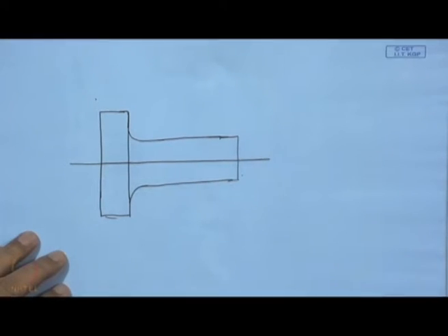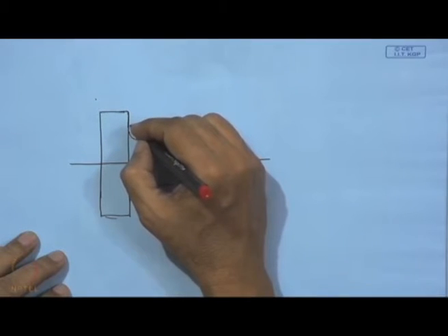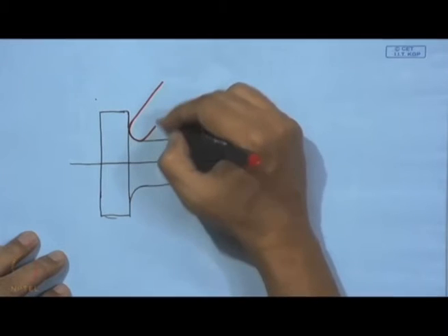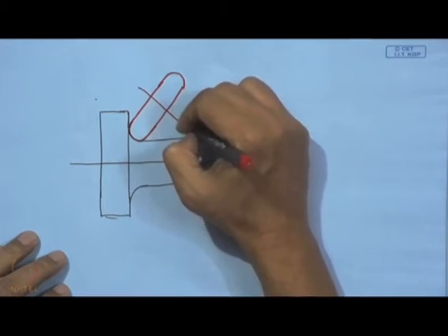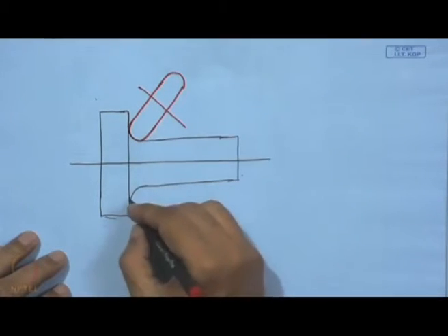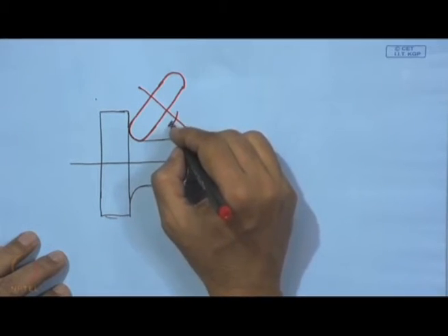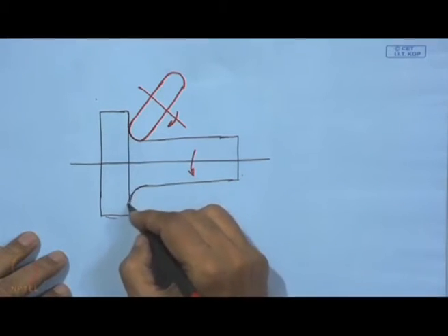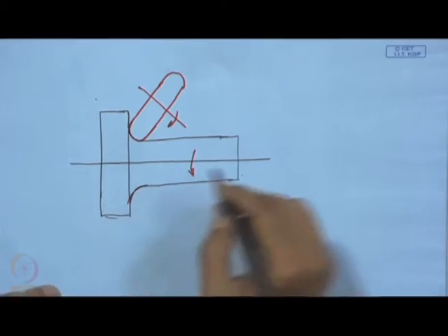However, there is still scope for using a roller in this zone, matching this curvature. Of course, its geometry should match the fillet radius, and this roller can spin while the job is also rotating this way. These are very delicate areas in the whole body, because it is going to spin.